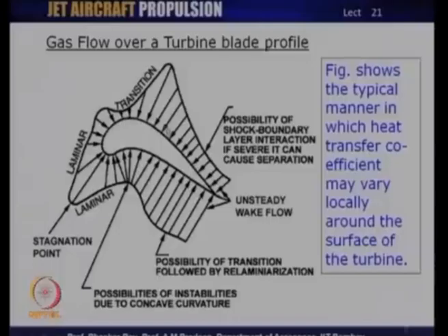So, depending on the blade curvature of each of the surfaces, the Cp, or coefficient of pressure, over the blade surface is continuously changing. So, the velocity field over the surface is continuously changing, and the local temperature is continuously changing. That means the heat transfer coefficient is continuously changing. This continuous change of local heat transfer coefficient means that you need to provide differential cooling at different points of the turbine. We have just seen that the stagnation point is a hot spot.